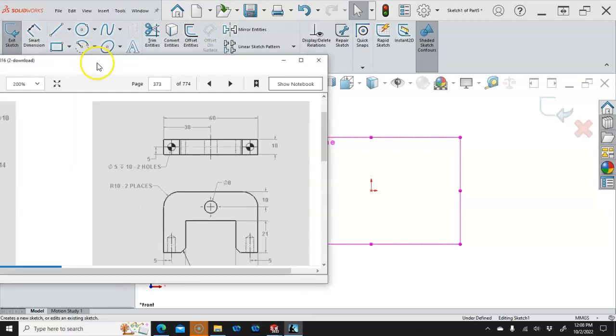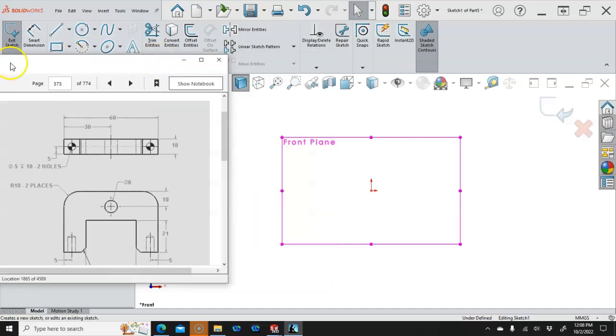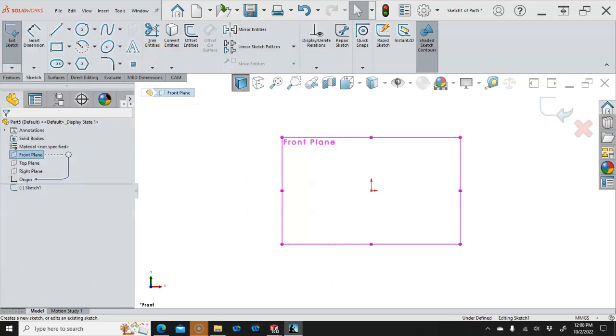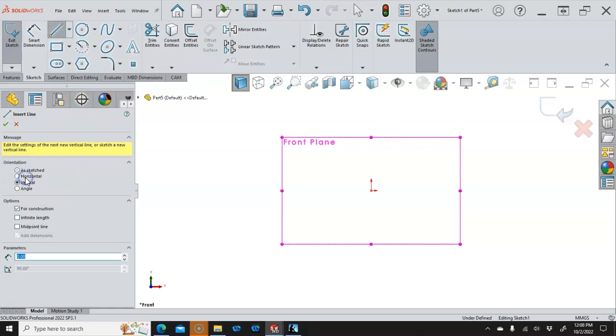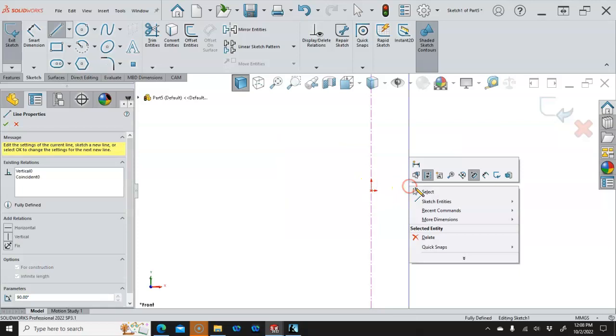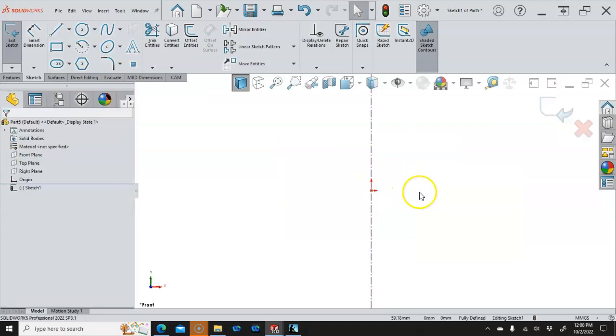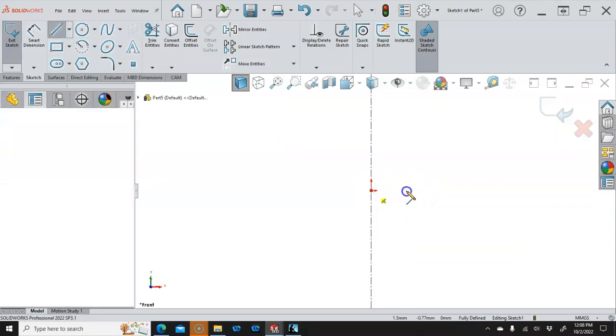Okay, so we're just going to make the bridge. We have symmetry. We have the same 5mm geometries, 5mm by 10mm depth on the holes, all pretty straightforward. A couple of radiuses, a couple of chamfers, some thoughts on the manufacturing center line, vertical infinite length. Place that, and then I'm looking to draw half of this, so L on the keyboard.